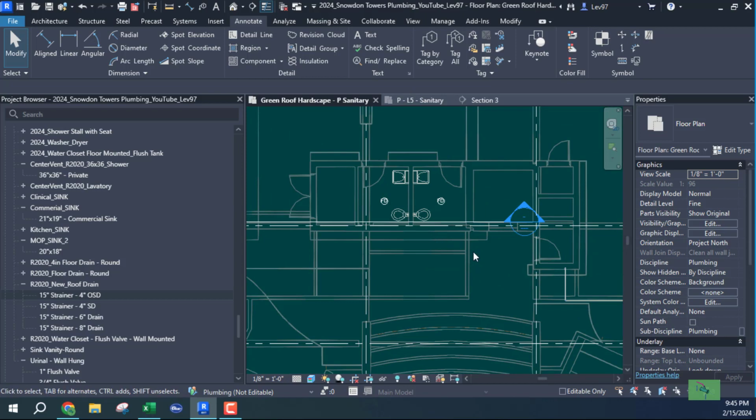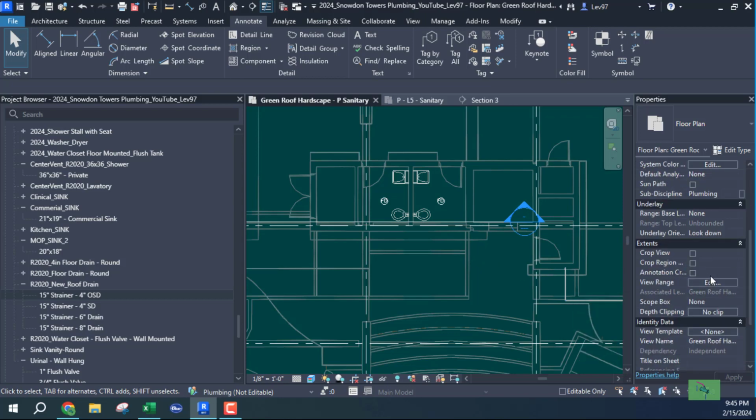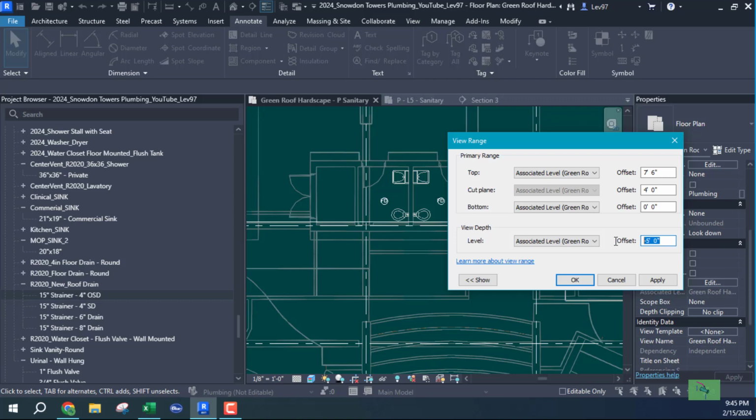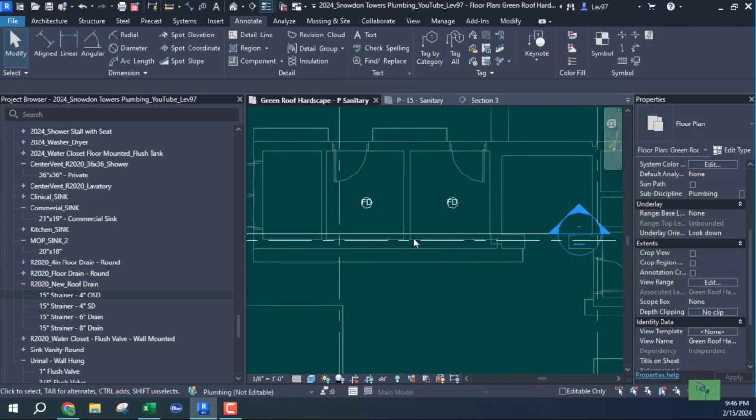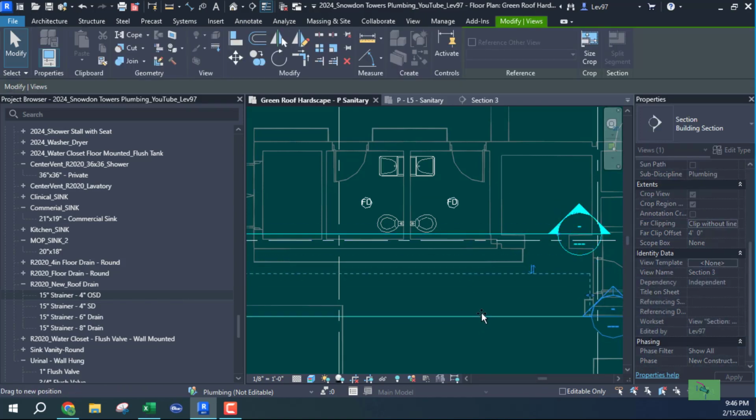What's this? That's on the bottom. That's the floor below. I think the reason is because the view range is a -5. Let's go back. See, -5. If it was 0, then it would be different. But it has to be this drainage. The drainage is going to be less than 0, which is a negative somewhere. And the reason that is showing, let's look here.